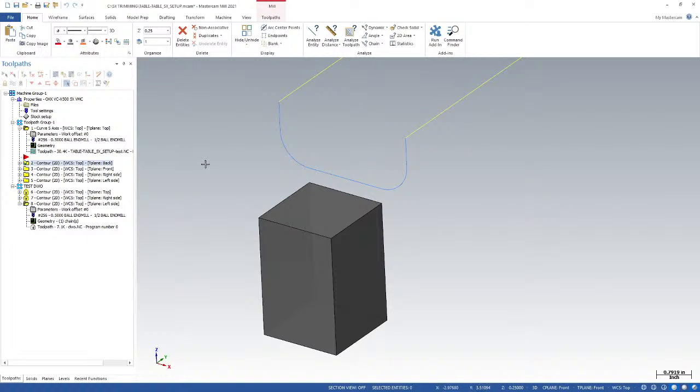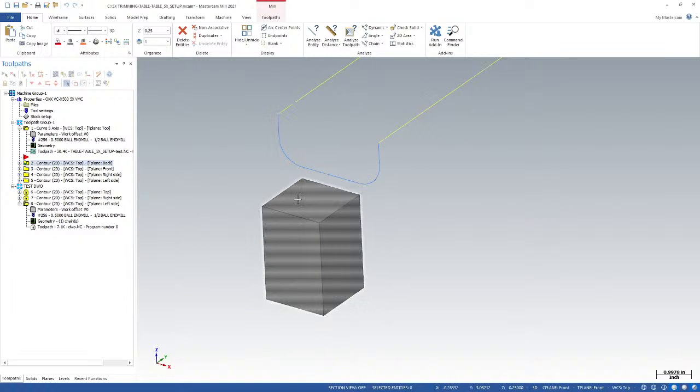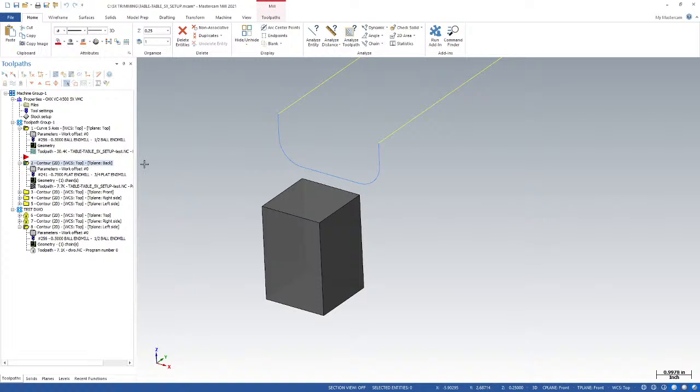Now, with a tool plane based toolpath, we've got our WCS, and we set a tool plane that is not parallel or matching to our WCS. And inside the post processor uses some vector mathematics and matrix math to resolve the z-axis vector of the tool plane. So if you go through and scour these operations in Mastercam, you're not going to see a rotary angle.